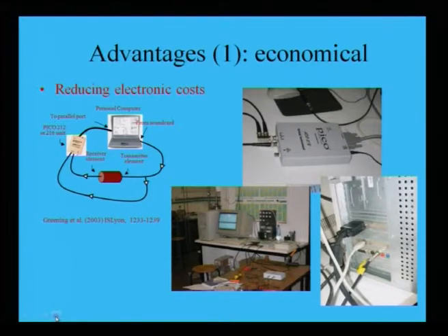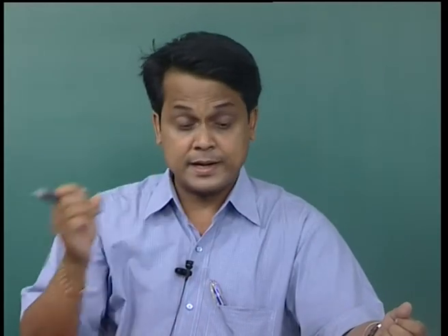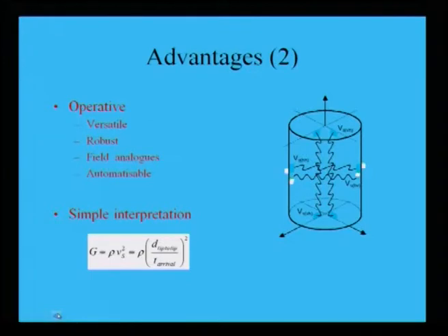So, the shear wave velocity can be measured from the source to the receiver. That means, in the soil element one end is your source, the other end is your receiver. Bender elements can be put at both ends and it reduces the cost. Basically in the field test the cost is very high. In the laboratory test it reduces the overall cost.